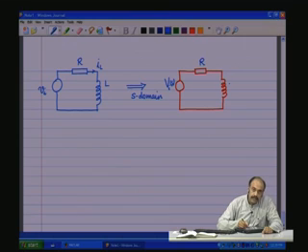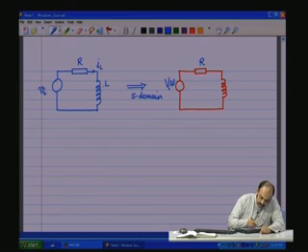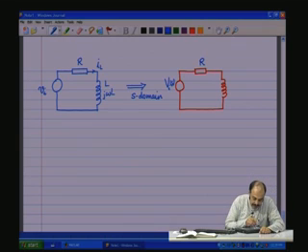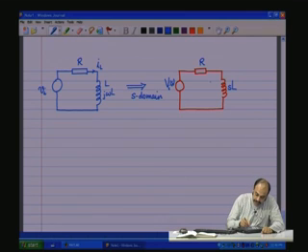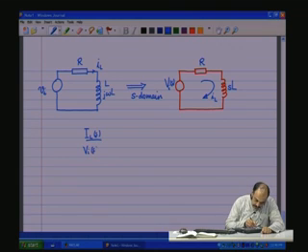Now, the inductive reactance, what was given here is normally j omega L in the case of the sinusoidal steady state, the inductive reactance, and here it becomes S L. Now, if you want to find, let us say, the current through the circuit IL, and you would like to see what is IL by Vi(S).